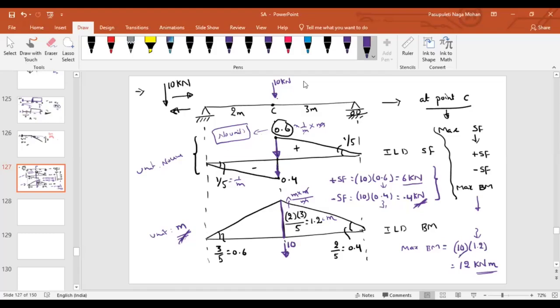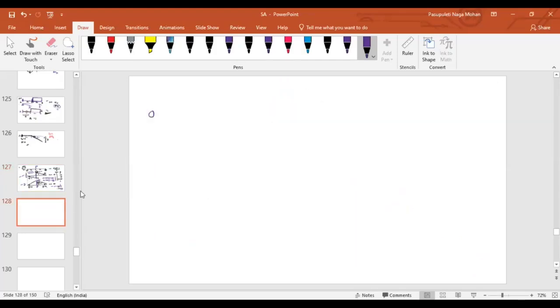If a bike is moving, you can say that two wheels will roll over the beam. That means you can idealize them as 2 point loads, isn't it? If I take a bike, I can idealize it as a 2 point load. If a car is moving, even if you talk about 2 point loads in two dimensions, but if you are talking about a truck,